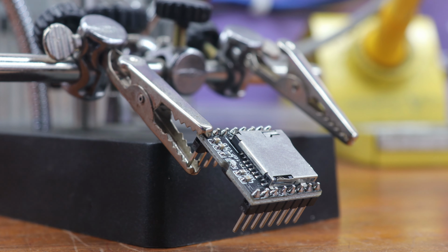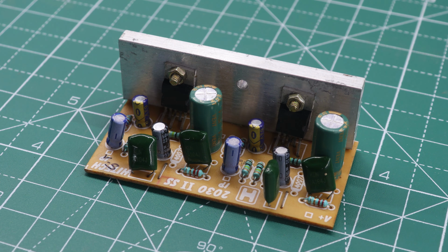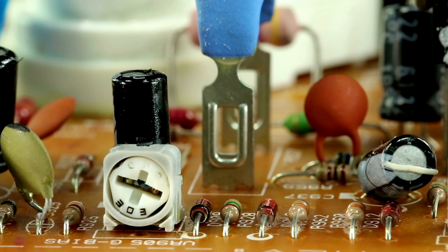The DF Player comes with a left and right audio signal output, so I am using a TDA2030-based mono amplifier module. This module uses two TDA2030 ICs in bridge mode to provide high amplification. You can use any type of amplifier module, such as a Class D, but in my case, I am using this TDA2030-based mono amplifier module.